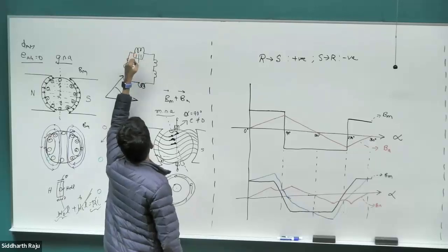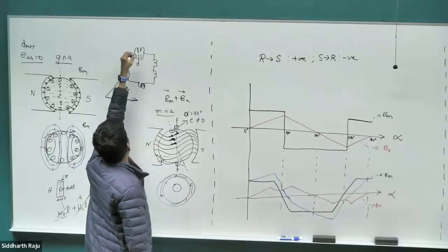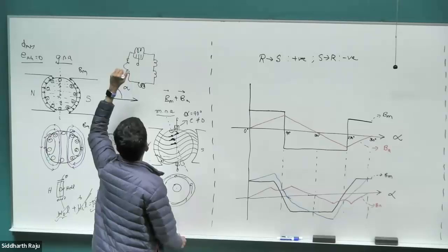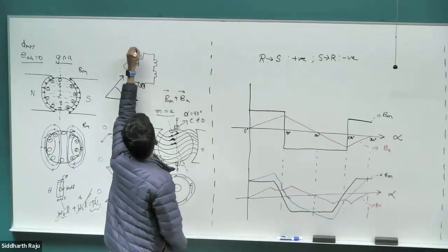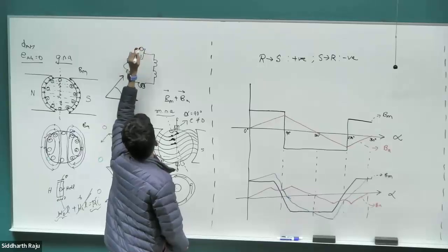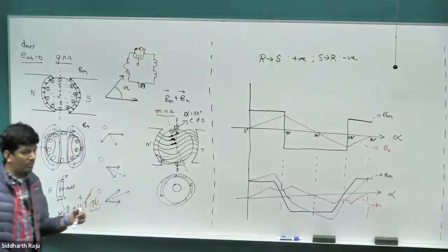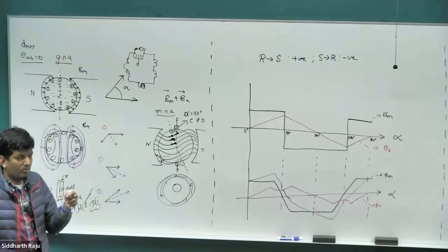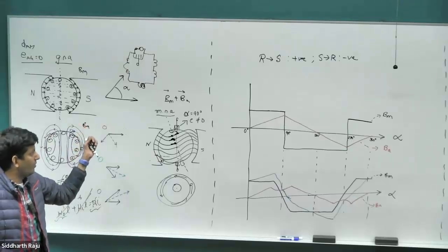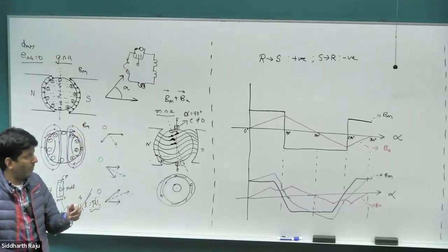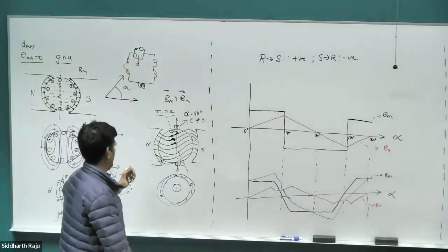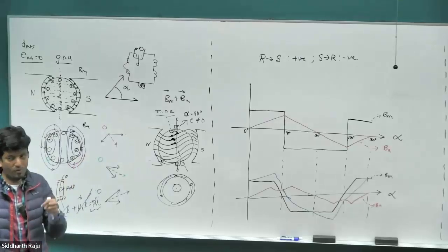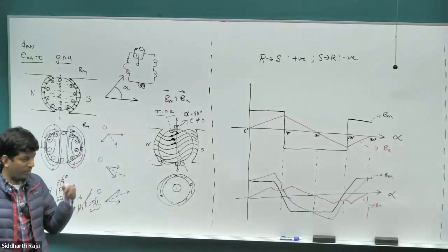So we had a brush which was shorting this commutating coil. Now this is not just an inductor coil alone anymore, because there is an EMF across it. So it's effectively an inductor coil in series with some voltage source. So we are ending up sourcing current through that coil. So it's going to delay the time it takes for the current to come down to 0. So by the time this brush moves past this coil and breaks complete contact with those conductors, the current wouldn't have gone to 0, and which then leads to arcing and sparking.